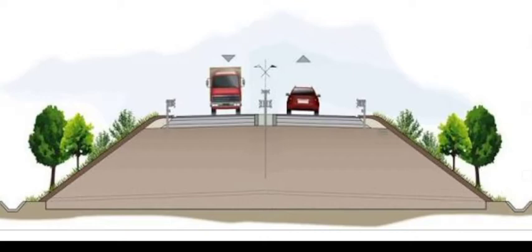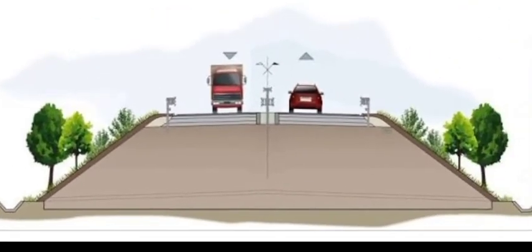When the original ground is flat without cross drainages, two longitudinal side drains are provided, as we see in this same figure. Both sides we are providing the side drains. If the original ground has a cross slope, meaning the natural profile is hill terrain, then only one side longitudinal drain we are providing, that is towards the hill, and towards the downhill there is no need to provide the side drainage.